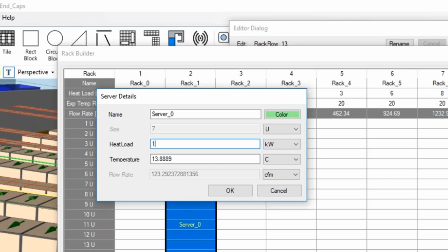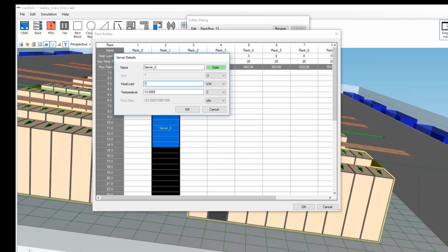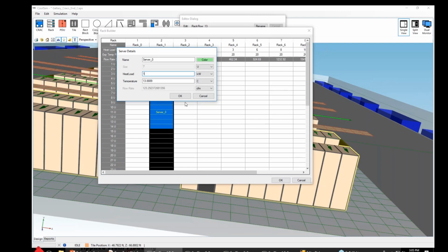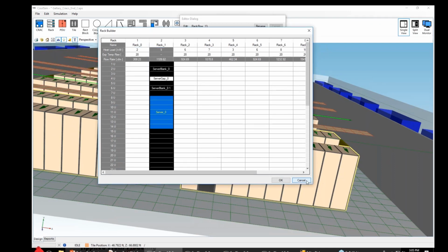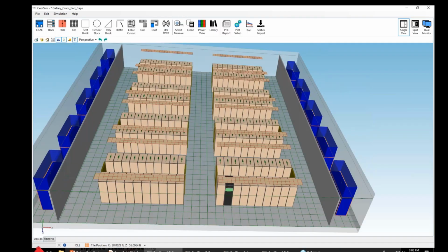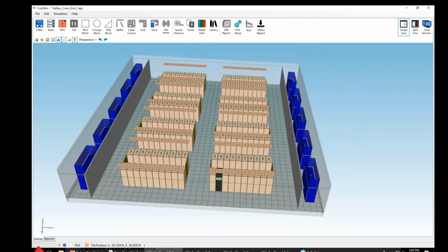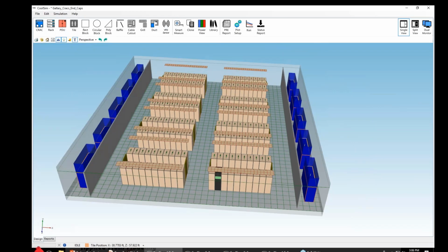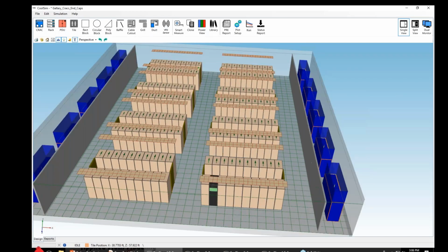How significant is static pressure to supply VFD performance? As I mentioned, I don't think static pressure is a good proxy for what's going on in a data center. It's my own personal experience, but as I mentioned, where do you put the pressure sensor, and how tight do you control it? It's a little bit like measuring carbon dioxide in a room to understand how well the humans are doing. Humans don't breathe carbon dioxide, so it's a proxy. Here, pressure is a proxy for inlet temperature. So what I'd rather do is just measure inlet temperature and drive it that way.